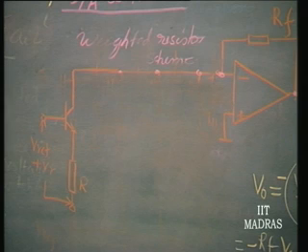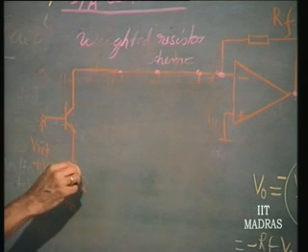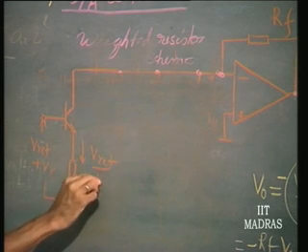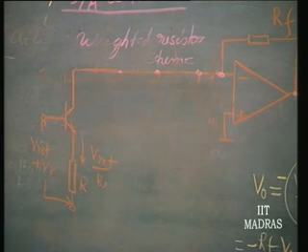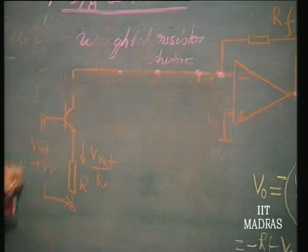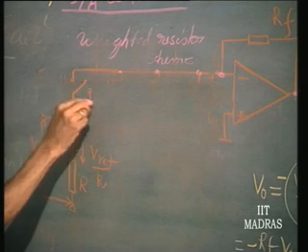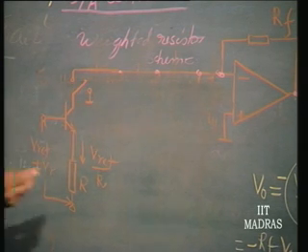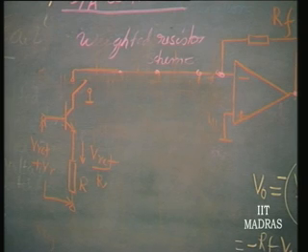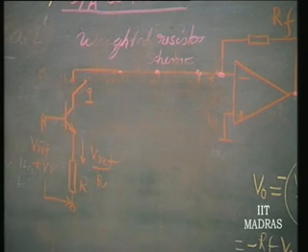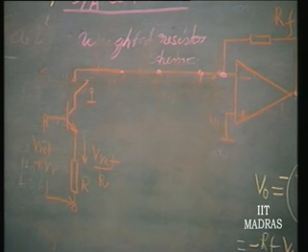Okay. Then the current in this is V reference by R. Now, you can introduce your switch at this point, either switching to virtual ground or actual ground. This scheme is what is normally adopted in most of the D to A converters ultimately.